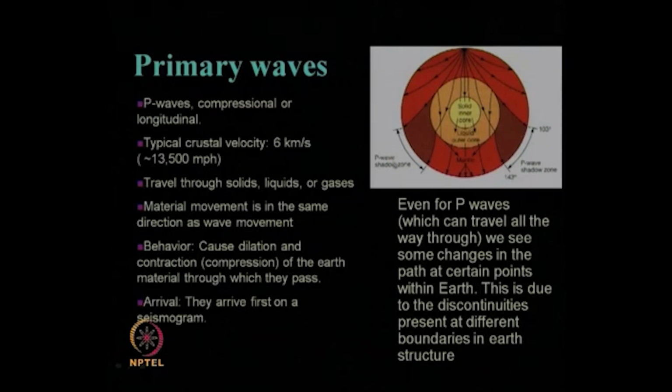We have also seen that whatever be the hypocenter or epicenter on the earth surface during an earthquake, the P waves can travel through all the various phases of the media of the earth, but still there will be a certain zone where the P wave cannot arrive, which is called the P wave shadow zone, and it is typically between 103 to 143 degrees from, if we consider this point as 0 degree. So, on both sides 103 to 143 degrees typically.